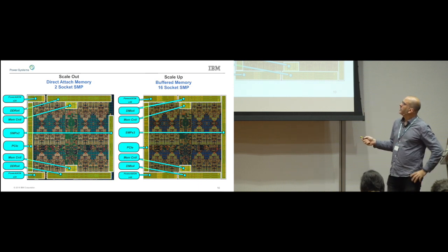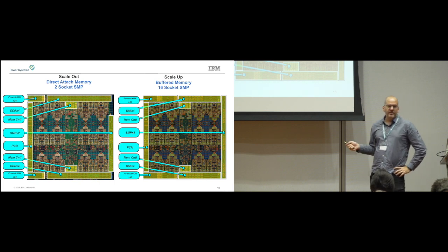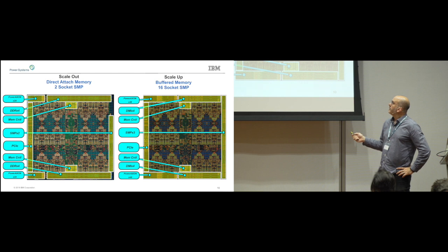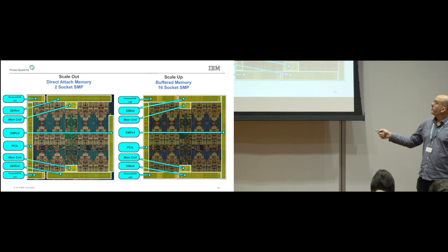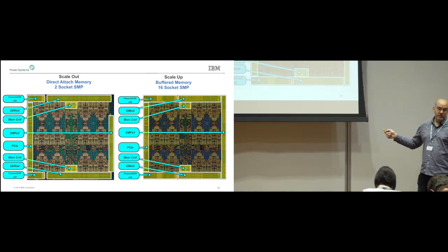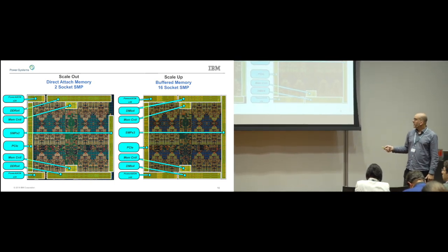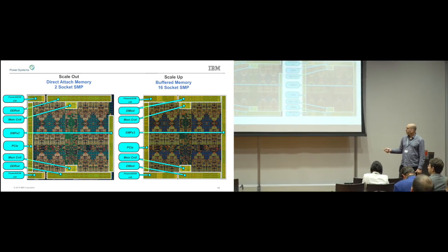So how do we do that, though? We take all the other stuff here, all this complicated, difficult to design stuff in the middle, we keep it the same, and then we change out components. In this case, the components we change out are 4 channels of DDR PHY, and this is 4 channels of DDR schedulers and controllers. And then you have another 4 channels of DDR PHY down here.